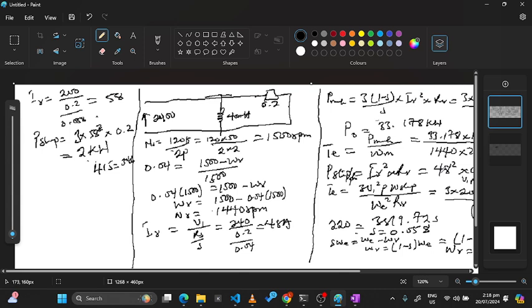I think we've actually increased the losses. Just changing this voltage, we've increased the losses from what, 1.38 to what? 2. Is that okay? Yes. So that's what happens if you do a variable voltage for an induction motor without varying the frequency as well. Okay, you are just going to increase the losses.